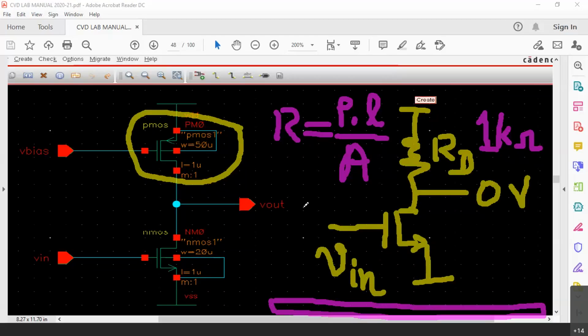So we are not discussing those devices which are going to be of bigger size. We are discussing those devices which can be implemented inside the chip with the smaller area. So the answer to this question is, the resistor is replaced with the Pmos just to save the area, nothing else.